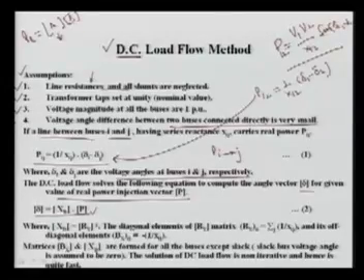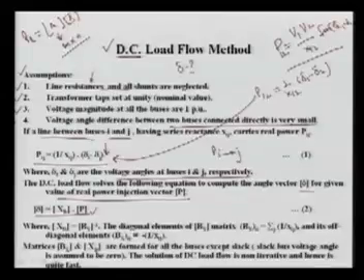In the DC load flow, what we do is obtain the deltas, and once you get the delta, you can calculate the line flows. That is required in real power security analysis, because we require the line flows: if some line is out, what will the power flow be? So we require the deltas from this expression. Here this matrix is M cross N, where N is the number of buses and M is the number of lines. The delta 1 for the slack is always assumed to be 0.